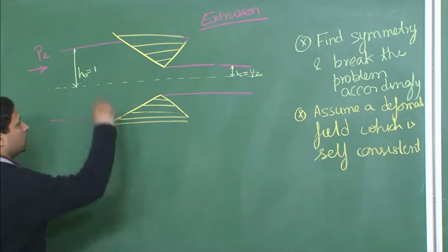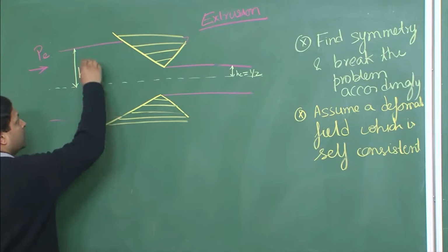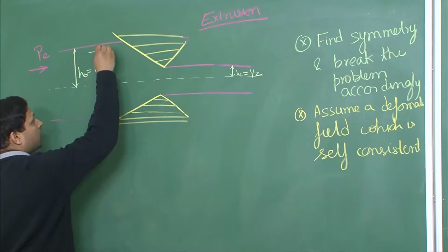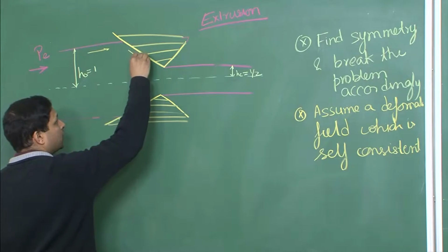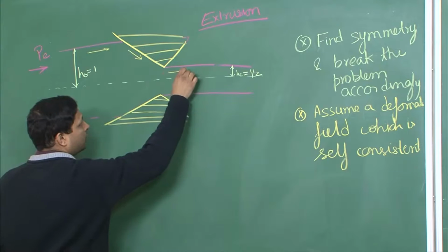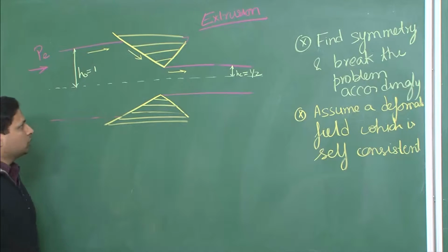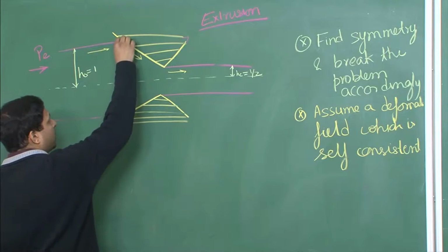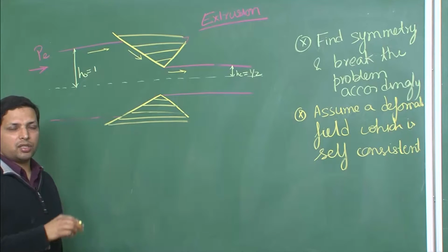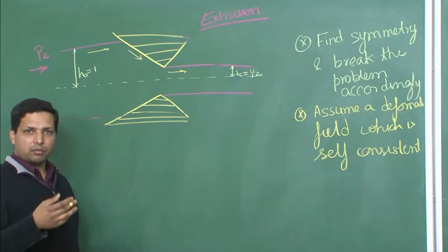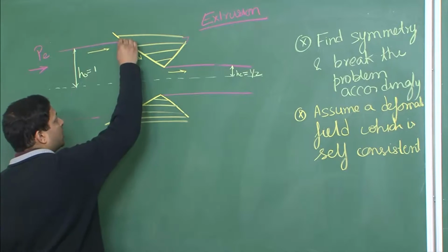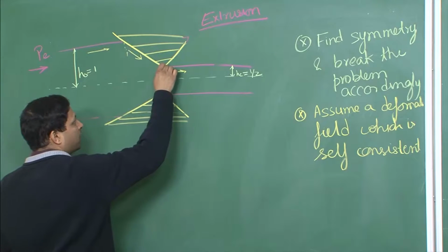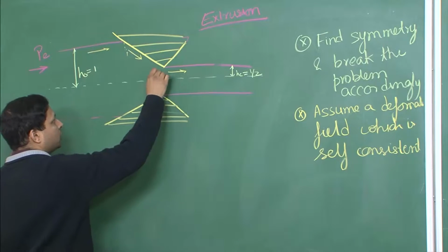So, what we can see here is what is happening to the material. We can see the material is moving like this, it is then moving like this and then it is moving like this. Now, this is the flow of the material and there must be a break in the velocity over here, which means whenever there is a break there must be some shearing going on. So, there is some shearing going on along this somewhere around this region. Similarly, there must be some shearing going on around this region.